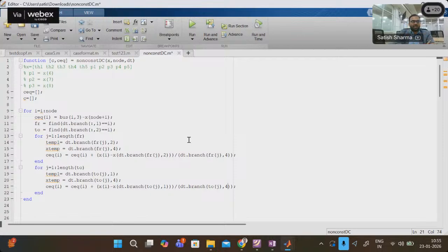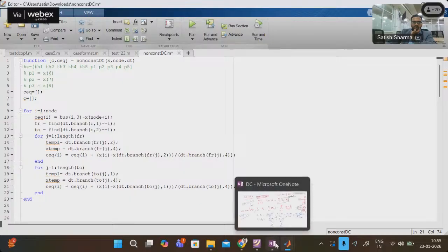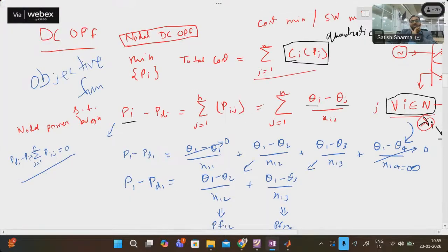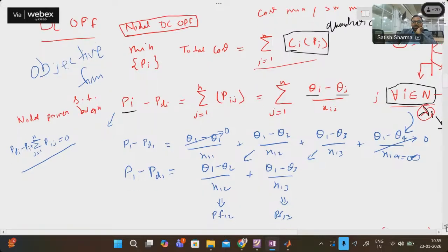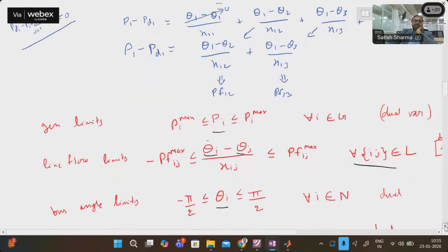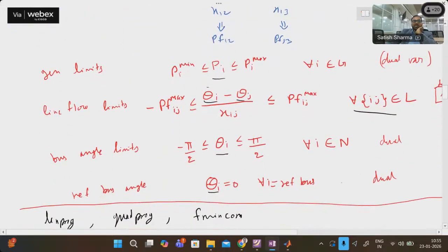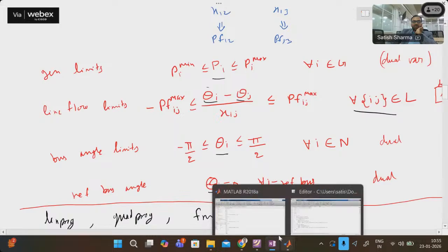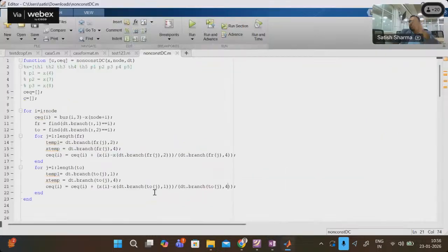Okay, as the time is going on, let's assume this is what, so C equality. Is anything else missing in C equality? If we go to the part, we have written down this one and we have calculated Pij, so that is over. Then we have to provide one theta reference, that is also an equality constraint, right? So I will put that as well here. Once everything is defined, this is like C equality.